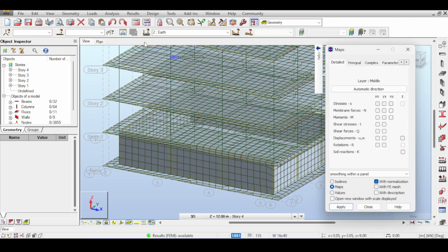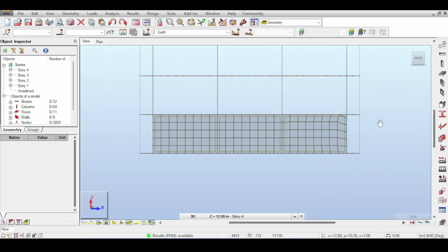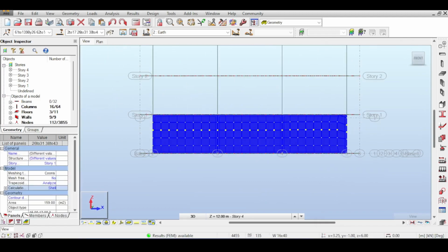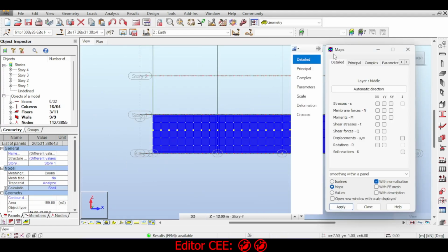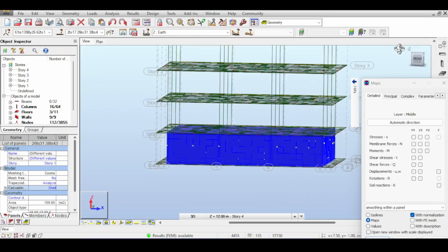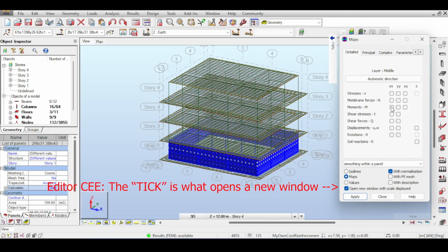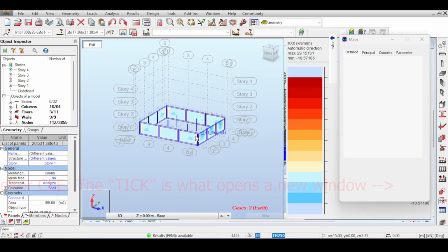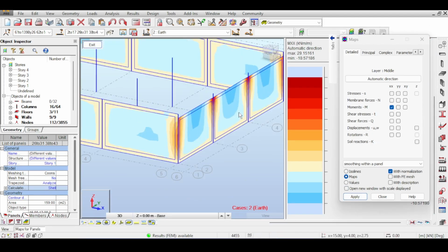So let me just open the earth load, which is the lateral load here, because dead loads will basically be the loads from the dead loads on the structure. But where you really see the moments is on the earth pressure. My bad, I was selecting the incorrect case. Of course, the editor is not going to make fun of me. I totally see this. I can see the future. So now I'm selecting the earth case, which is the lateral case, and now it should be making sense. So let's go to MXX, hit the apply button, and now it makes sense. Now it's correct. Now this is what I was expecting.